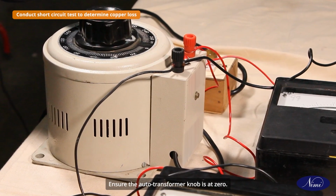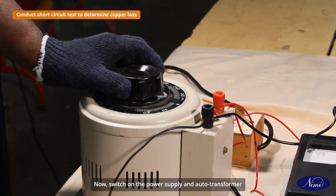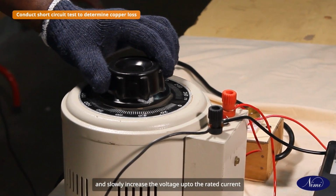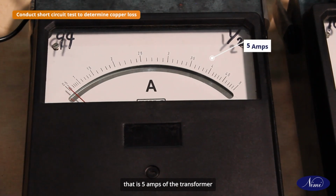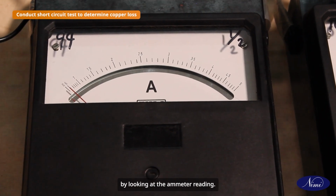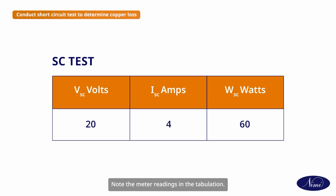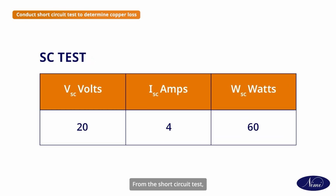Ensure the auto transformer knob is at 0. Now switch on the power supply and auto transformer and slowly increase the voltage up to the rated current, that is 5 amps of the transformer, by looking at the ammeter reading. Note the meter readings in the tabulation. From the short circuit test, the copper or variable loss is to be calculated.